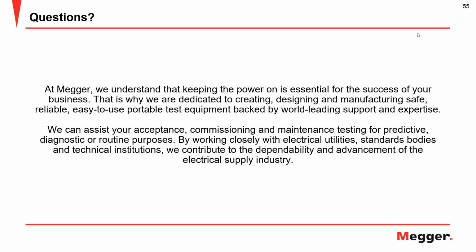Now, in terms of the magnitude itself, here we're talking IEC picocoulomb, and IEC 60270 defines your frequency bands and where you measure, how you measure, what you filter, what you cannot filter, all of these things. On top of that, the test that you mentioned is a factory test.